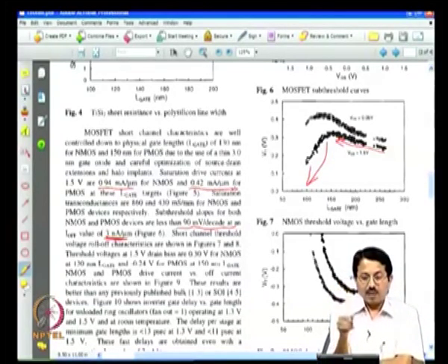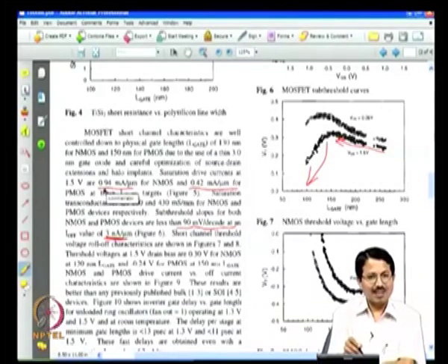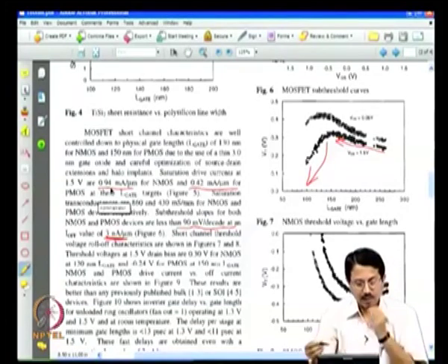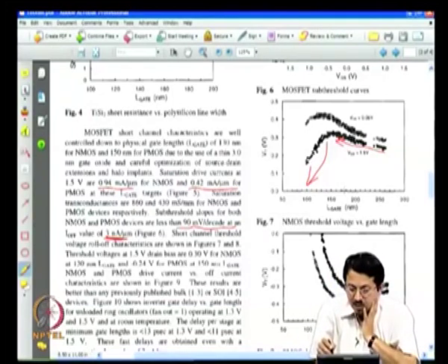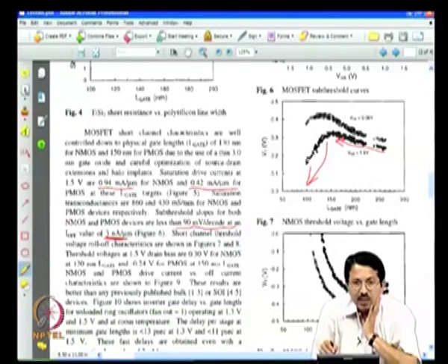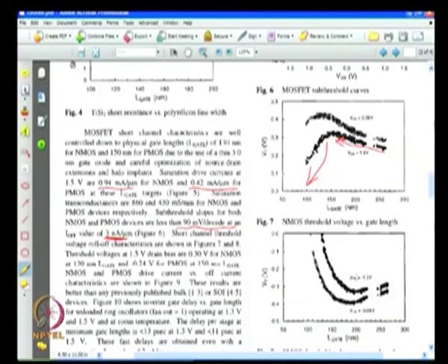Okay. So, in other words, your on current to off current ratio is almost 10 power 6. If it were to be 10 power 6, then it would have been 3 milliampere here, but it is not 3 milliampere, it is close to 1 milliampere, correct, okay, which is reasonably good on current to off current ratio. This is NMOS, this is PMOS, same story, reverse short channel effect and typical VT roll off. The VTs are negative, again lower drain voltage, higher drain voltage. Okay.